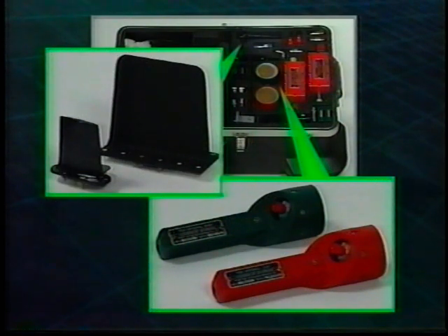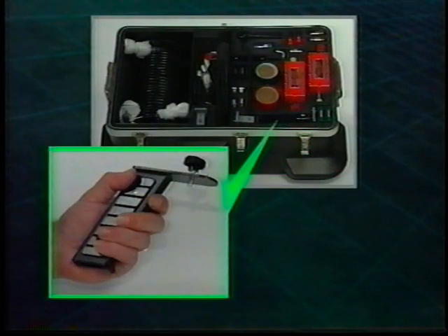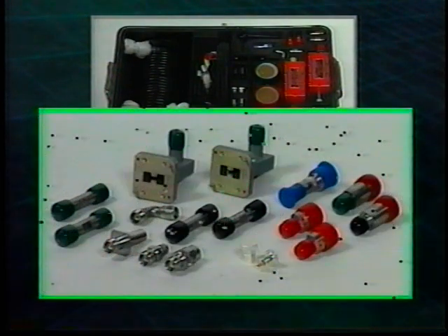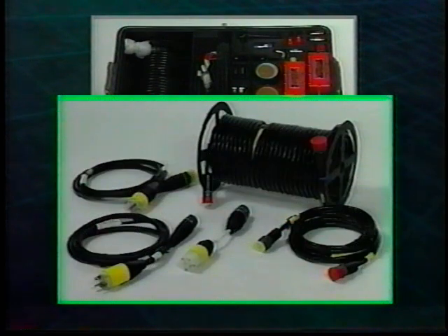The green right-hand circular polarized and red left-hand circular polarized antennas both cover 2 to 18 gigahertz. The low band covers 10 to 500 megahertz, and high band covers 500 megahertz to 2 gigahertz. Other accessories include a handle which can be attached to the blade antenna for radiating testing, adapters, connectors, 110 and 220 volt power cables, 15-foot and 105-foot video test cables, and 25-foot RF cables.